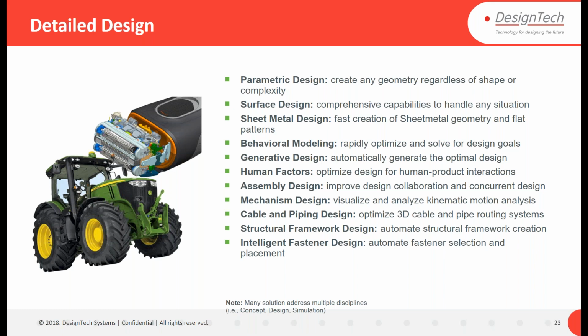There are other options like intelligent fastener design. I have seen that while designing, people sometimes create all the holes in the component to make sure that when they place the fasteners, the holes are there, right? But in our case, it doesn't have to be. Just define the location of the hole or the fasteners, and it will automatically create the hole while applying the fastener.